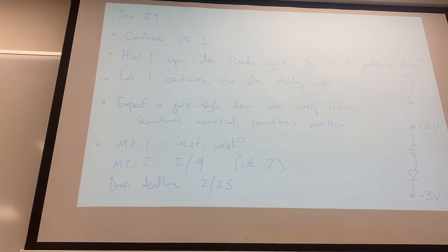And then their fourth most extreme method is to use the actual exponential diode equation. That's something you can't really do on paper. You usually have to pull up a computer in order to solve that. We don't want to do that here anyway. So the two chapter 3 problems I've specified problem part B in both cases, and subpart B is to use the constant voltage drop model.